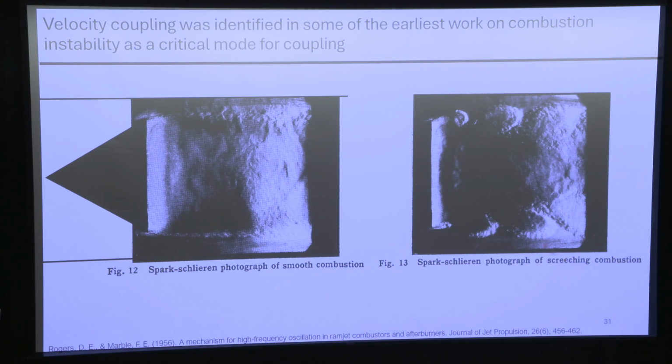and you can see that there are these large-scale structures in the flame. I will be the first to say that one should not infer a velocity field from a Schlieren photograph, but we're going to infer a velocity field from a Schlieren photograph because you can really clearly see that this is vortex roll-up on the shear layers that are separating off the bluff bodies, right? The other thing to notice is that this is anti-symmetric. So if you drew a line, here's the first little vortex. It doesn't have a partner up here. This one is in the braid of this one.